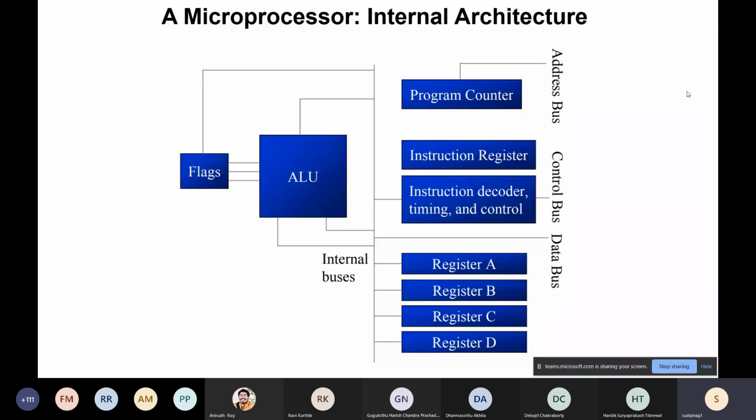So the address bus carries the address, which memory location, from the address range that we discussed in the previous slide. Then you have to get the data. The data from the memory will come through the data bus, and through the control bus we control whether it is a read operation or a write operation. So memory will understand what the microprocessor is trying to do.